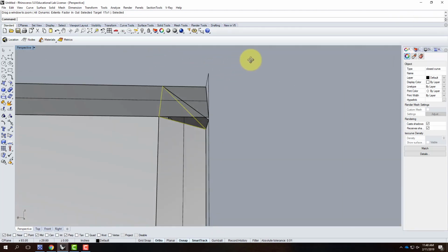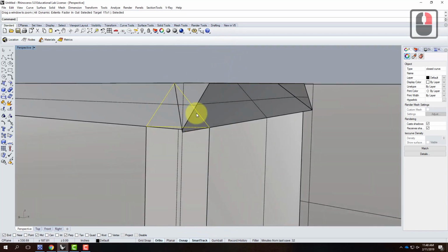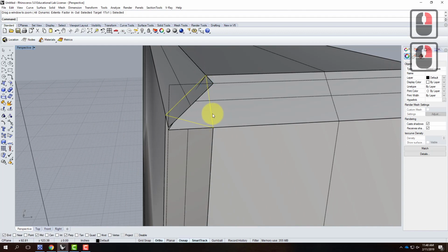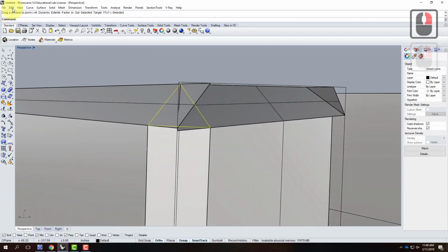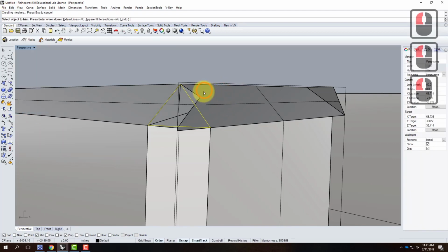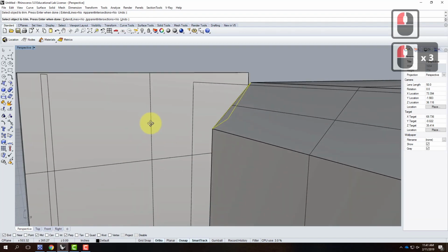I have my chamfers, that's good, and it's hollow, but I've got these two pieces of surfaces that are just kind of hanging out there. I need to get rid of those. So I'm going to go in and use my trim command. I have that triangle still selected. I will choose the trim tool, or I'll type trim, or navigate to edit and then trim. And I'm going to get rid of these pieces that are sticking out past my triangle. And there they are.